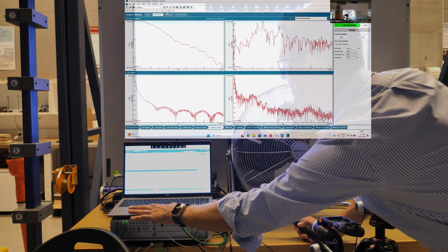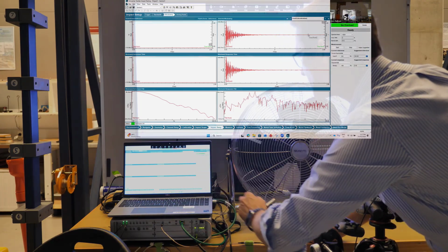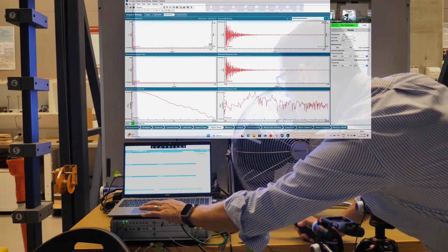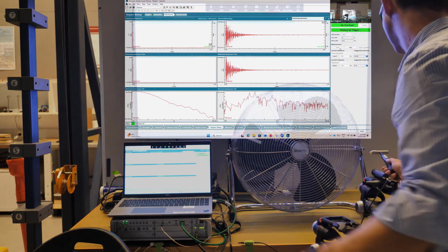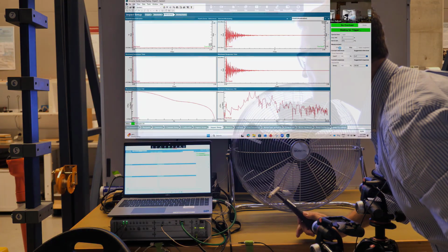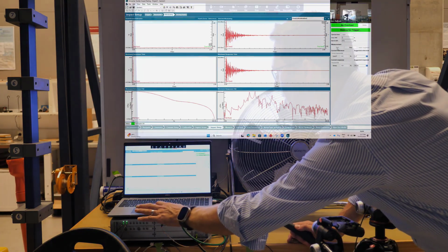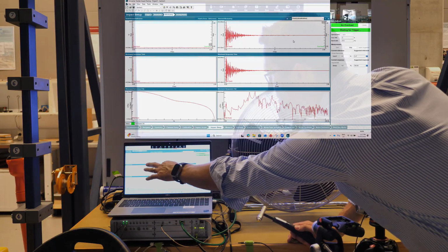If I come back in here and set some windows up, I'm already getting quite nice output with a force exponential window, so with a rectangular window. So if I do an impact, it's measuring for 2 seconds, and I get some audio feedback. The response decays very nicely to 0 by the end of the 2-second acquisition.